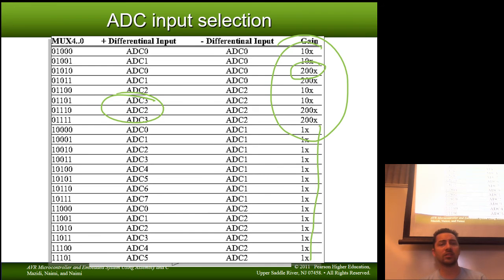Because if you get an external ADC, because the ADC on the 328P, it's not a one-size-fits-all. It can only go so fast. It's only got a 10-bit resolution. You might need a 12-bit or a 16-bit resolution. You might need to go faster. You might be able to get away with only an 8-bit resolution, but need to go much faster. So those are all things that you need to deal with. So be aware that you can get ADCs that do this.